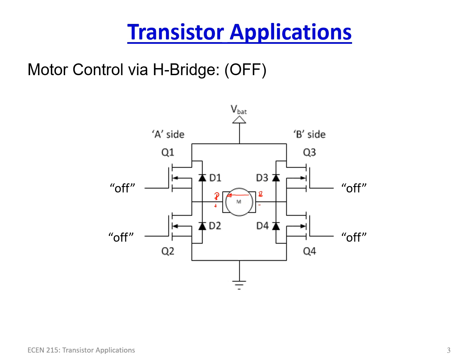So based upon the current flow, I can have the motor go forward and backwards, which is a useful thing, especially if you're controlling position or something. Now, how do you do this? By using an H bridge.